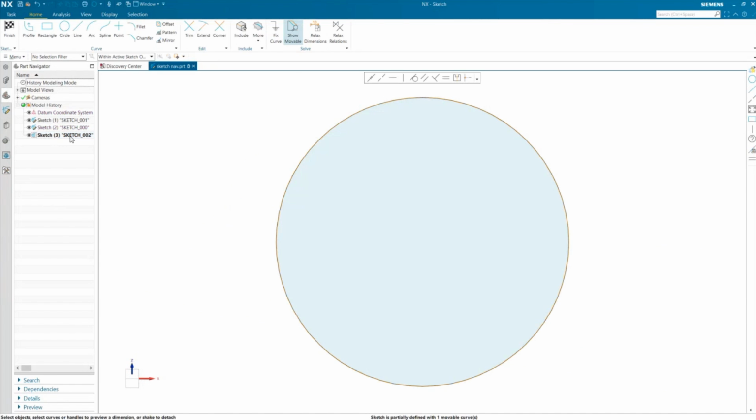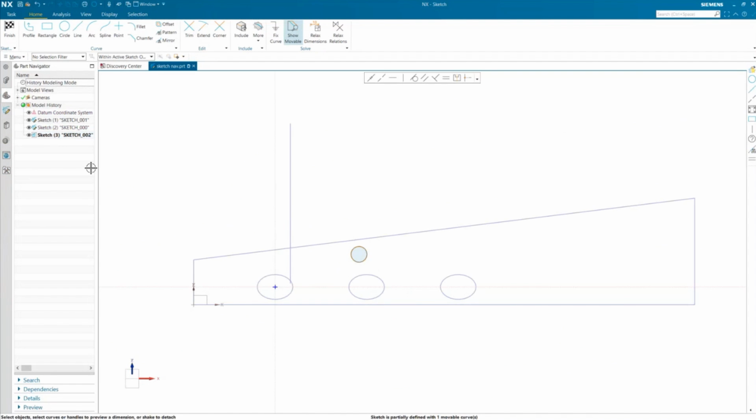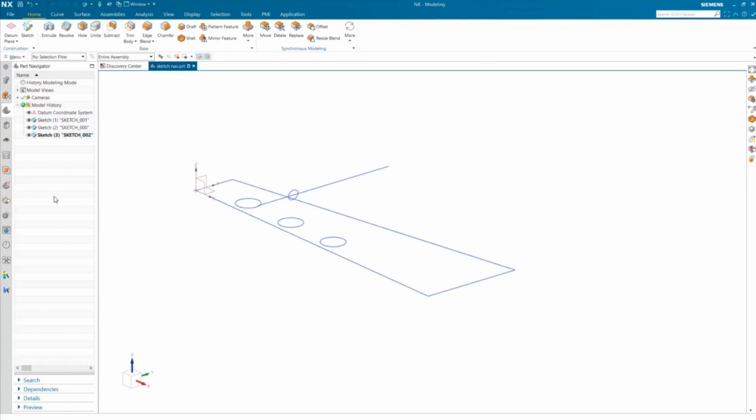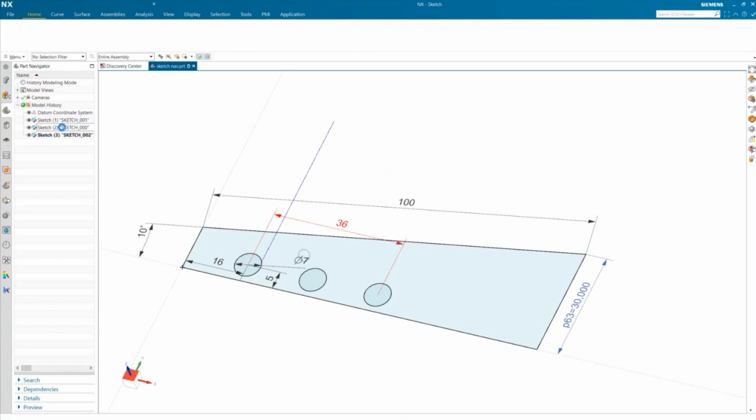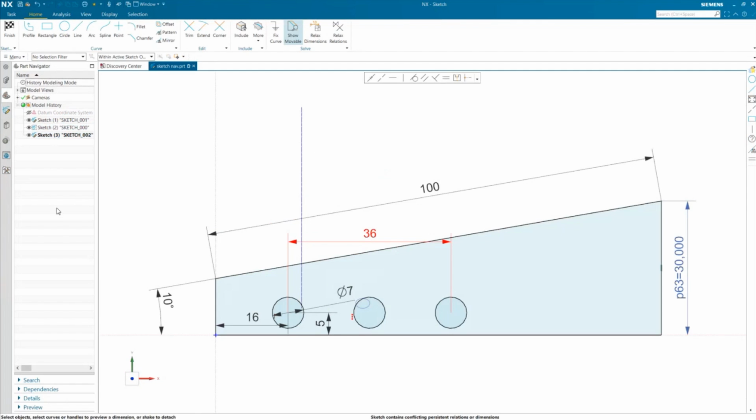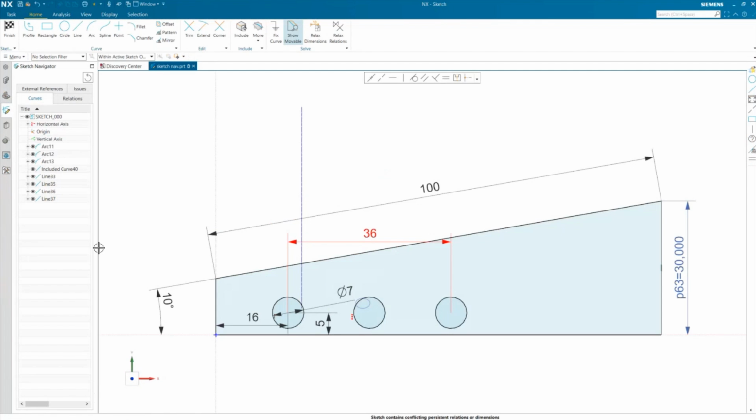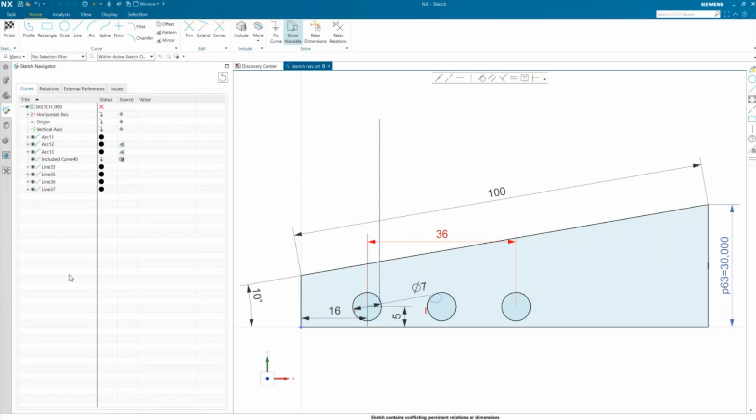Okay. So, Sketch Navigator, let me get into the other sketch. That sketch there is not the sketch I wanted. I wanted this sketch. The Sketch Navigator is a tool that's been added in 2406. It allows me to go in and see what my sketch has. In here, think of this as non-movable. You see the circles there? Think of it almost like the Assembly Navigator. If it doesn't have the circle, it's telling me I can move that particular dimension or line.